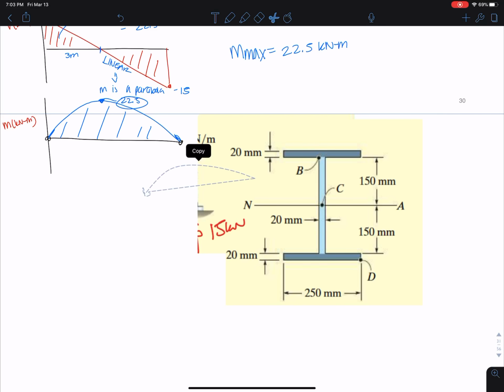We know that moment of inertia for a rectangular section equals 1/12 BH cubed. That's a really easy formula to memorize because I don't want to memorize a bunch of different moment of inertia formulas or derive them from dx, dy integrals. So I want to stick to this if I can use it. And I can, because all I have here really are just 3 sections.